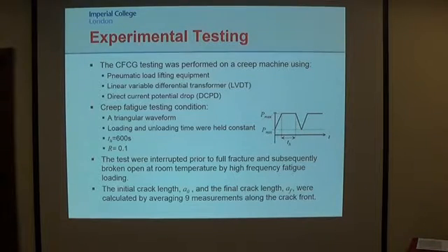So the creep fatigue crack growth testing was performed using pneumatic load lifting equipment, and the LVDT is used to measure the load line displacement, and the DCPD technique is used to monitor the crack length. So a triangular waveform is used where the loading and unloading time is constant at approximately 2 seconds.